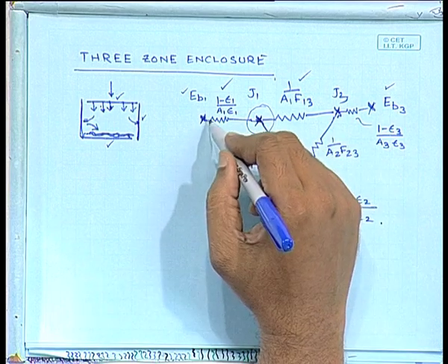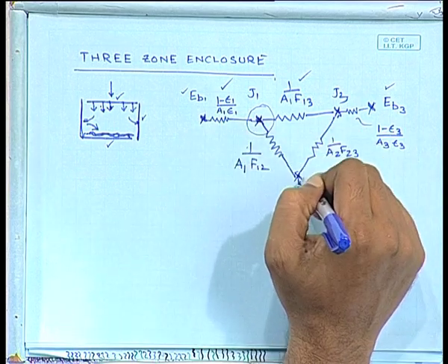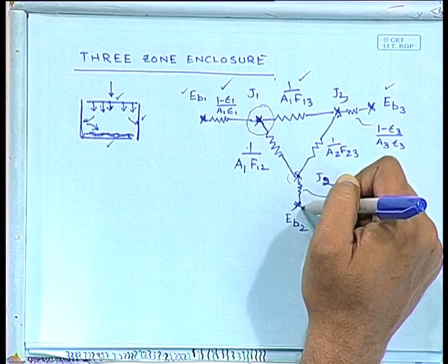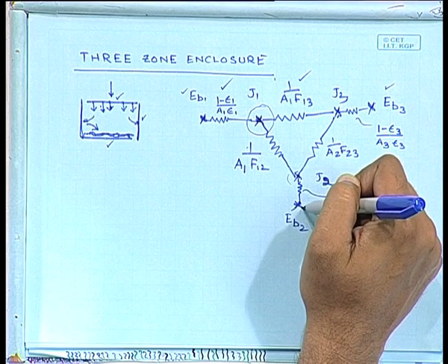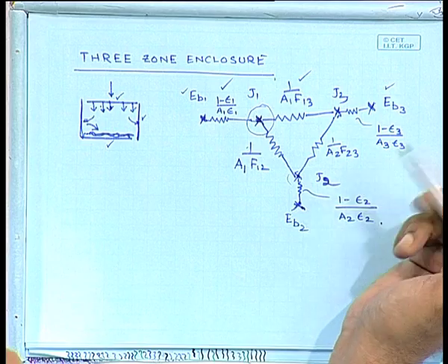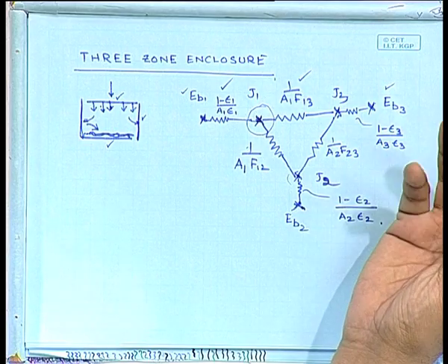Okay. So, utilizing all those, you try to find out what is the value of J2. Since epsilon 2 is known to you, you can calculate what is the value of EB2. The moment you know the numerical value of EB2, it is equal to sigma T to the power 4. T2 is the only unknown.